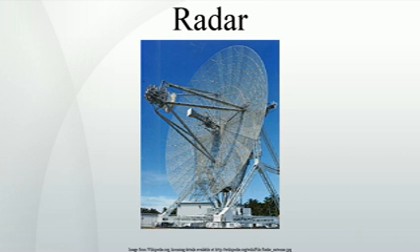Constant false alarm rate, a form of automatic gain control, AGC, is a method that relies on clutter returns far outnumbering echoes from targets of interest. The receiver's gain is automatically adjusted to maintain a constant level of overall visible clutter. While this does not help detect targets masked by stronger surrounding clutter, it does help to distinguish strong target sources.